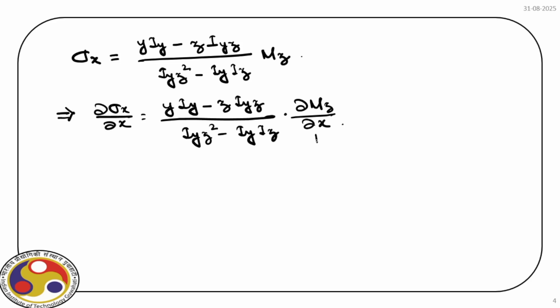So we know this is equal to the shear force acting at that particular section. Now what we get is tau xs or tau sx is equal to minus 1 by t, integral 0 to s, differential of sigma x with respect to x times t times ds.